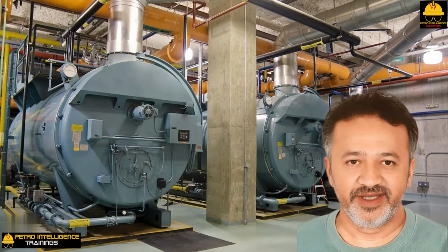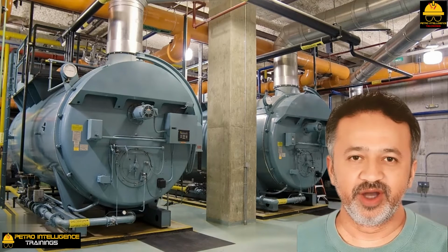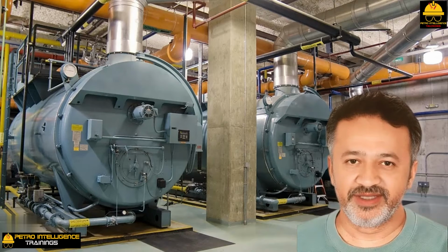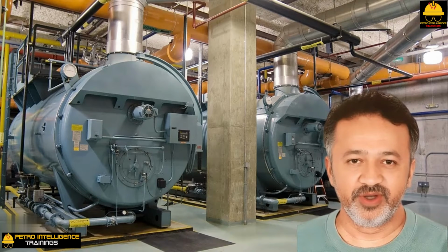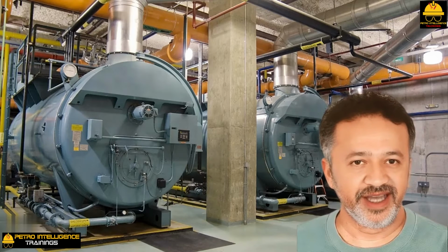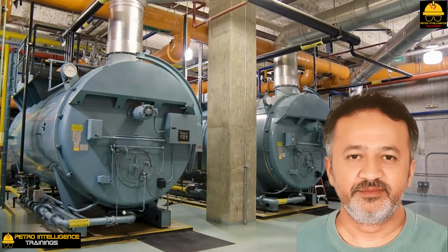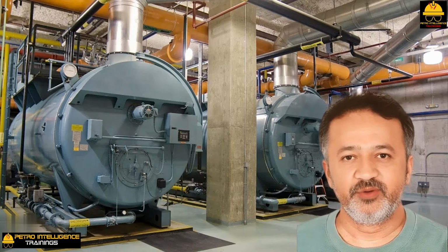In former days, hot lime water softening was employed. In most modern process units, ion exchange resin is used to demineralize BFW. Blowdown is the water that is drained out of the boiler to control the accumulations of TDS or silicates in the boiler. Some people drain 10% of the makeup BFW flow.